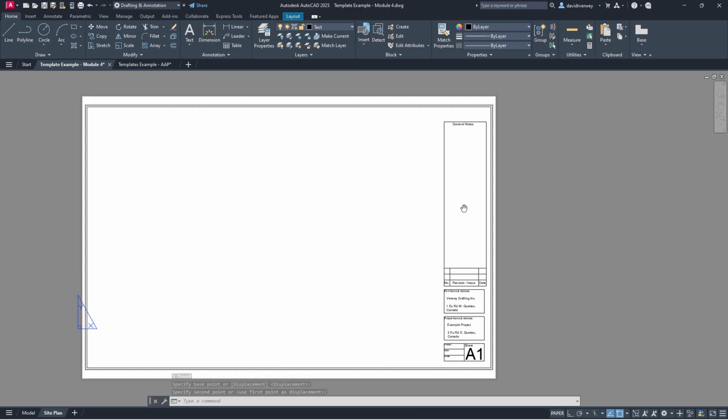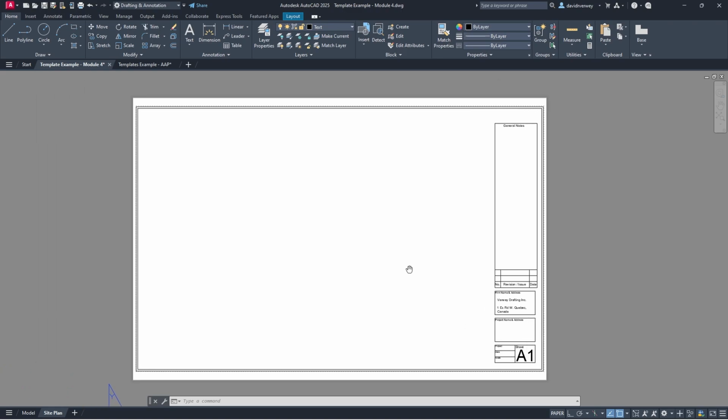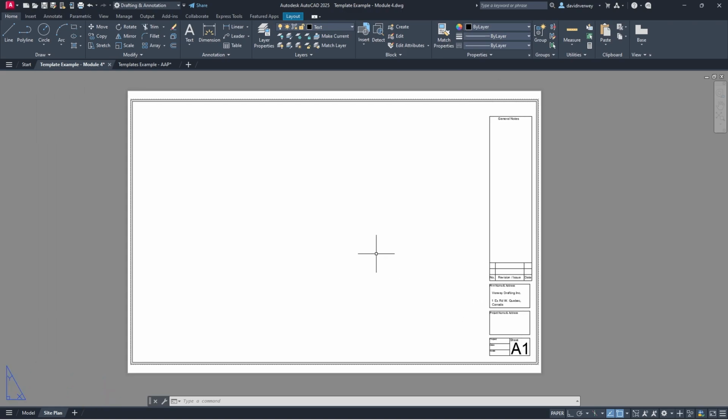And there you have it. So this is adding text to your title block. So then what I would do in this case is I would get rid of the project and I would get rid of the sheet as well. And then I would leave my firm and the address on there, so that's always there and I don't have to type it in all the time. So then you have your title block and you're pretty much set and ready to go for the most part.